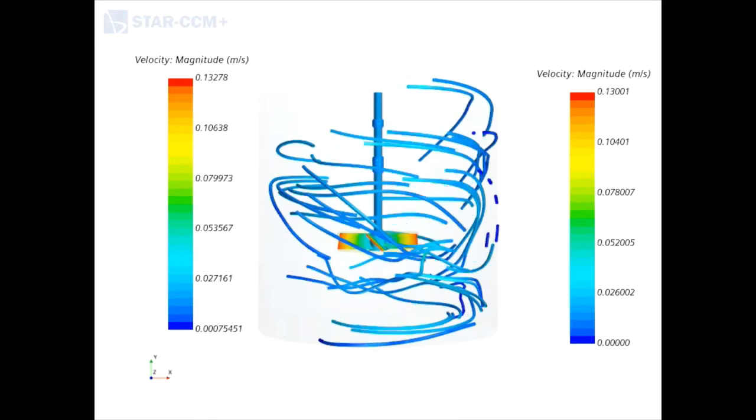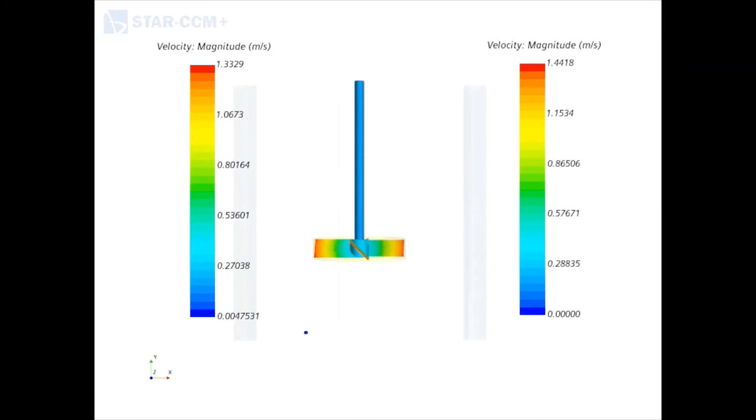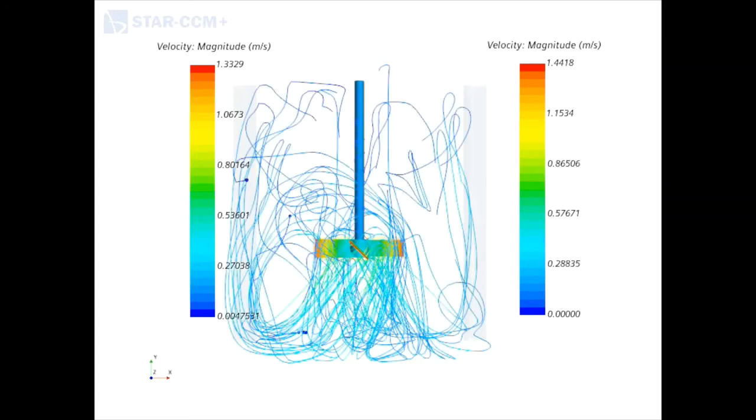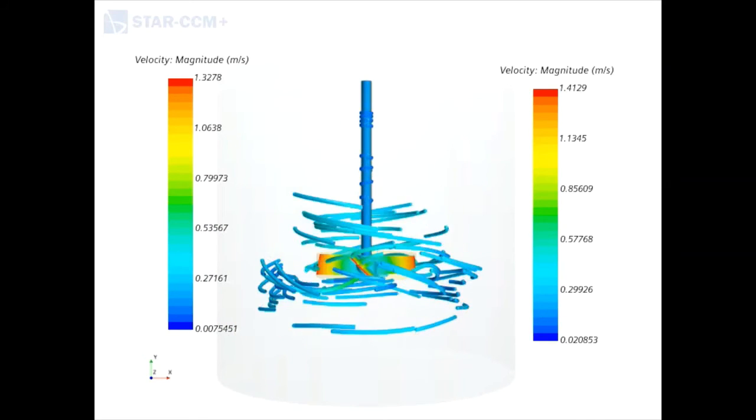In a tank without baffle plates, the circulatory flow will predominate regardless of the type of impeller used, whether the flow is axial or radial. At high rotational speeds, the depth of the vortex can be so great that it reaches the blades, causing the gas above it to enter the liquid, which should normally be avoided.